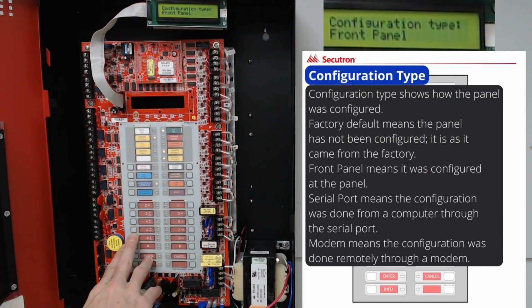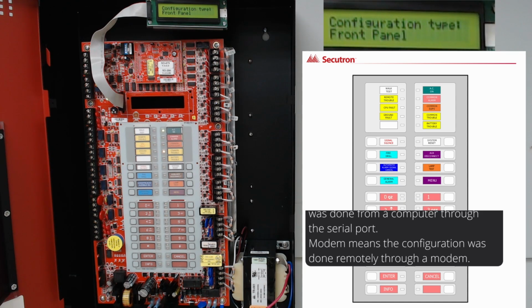Currently, the panel is telling us that the configuration type was programmed through the front panel. It could also display factory default, which means that the panel has not been configured and it is the same as it came from the factory. Serial port will indicate that the configuration was done from the computer through the serial port. And modem means that the configuration was done remotely through a modem.